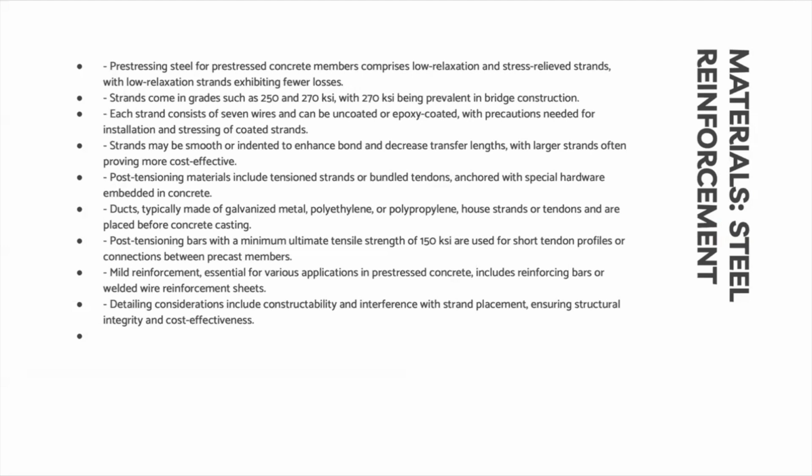While stress relieved strands are no longer referred to in the AASHTO LRFD bridge design specifications, they do still remain in use for evaluating existing structures. Typically, low relaxation strands exhibit fewer losses compared to stress relieved strands.